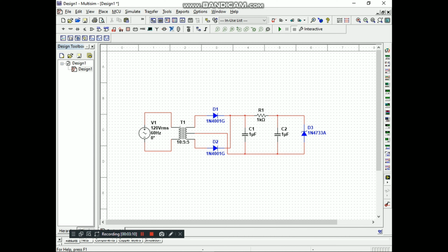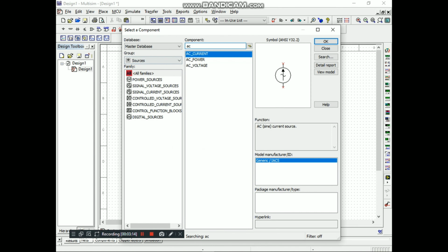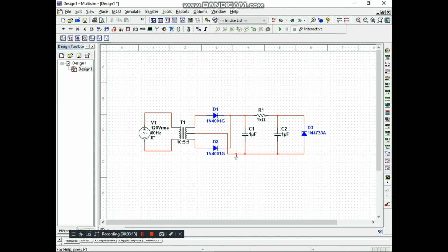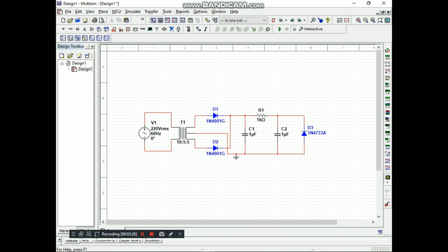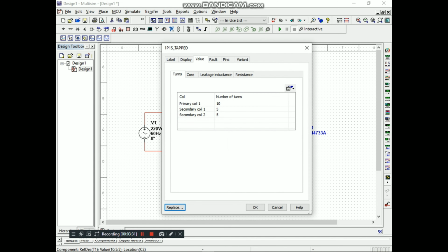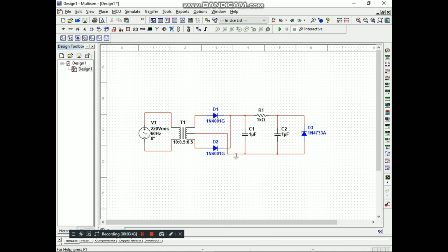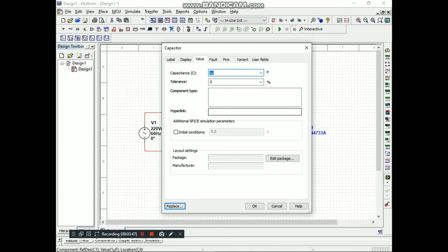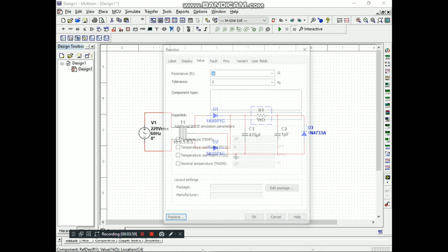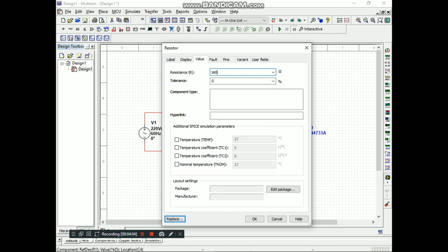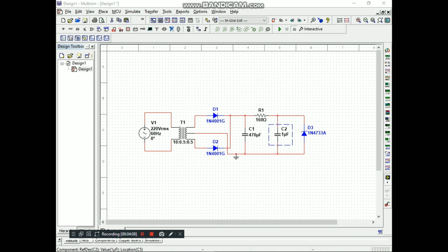An output voltage independent of the load is always required. In this circuit, I use a 1N4733A Zener diode with a voltage of 5.1 volts and a power of 500 milliwatts, which will give me a current of 98 milliamperes. I use this diode because my desired DC voltage output is 5.1 volts.